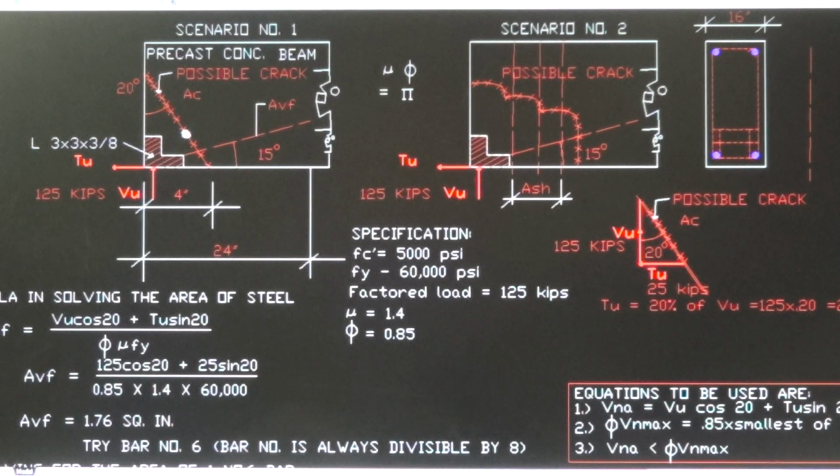the face of the cracks, both faces, this side and that side, has a concrete friction of 1.4. The friction depends on how the beam is constructed. This beam is constructed monolithically. It means the concrete is poured together at one time, so it has a coefficient of friction of 1.4.